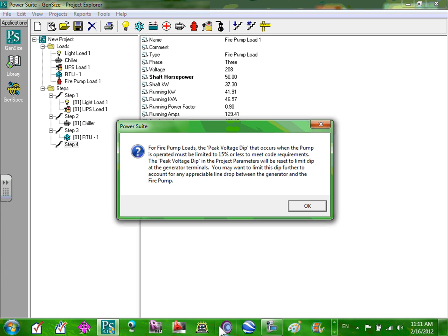And after we get it covered, we might see what our set is after we get all of this done. And what I do, and there's no magic to it, is pick a 70% generator loading, because all of the loads that we plug in there, if we take an average day when the power fails, maybe all these things aren't running. But we've sized it so it is all running.